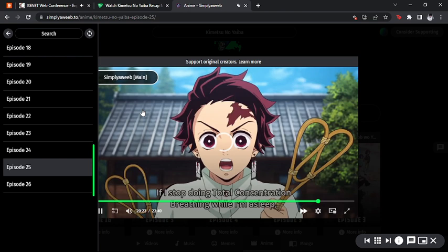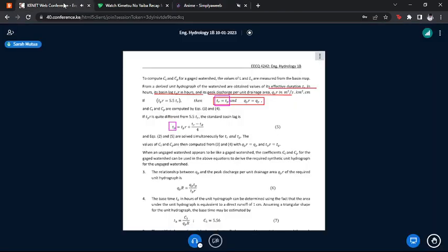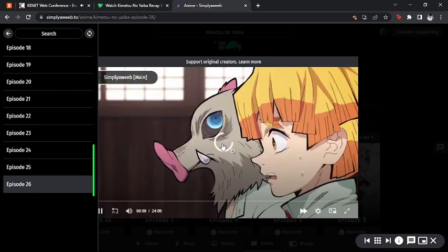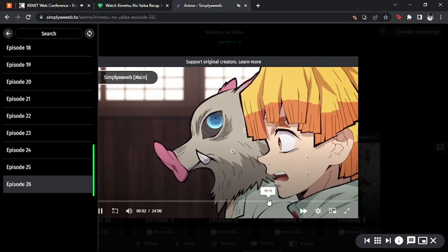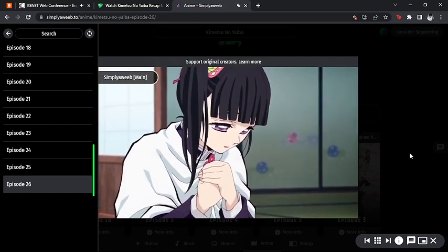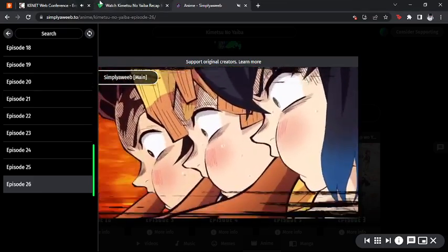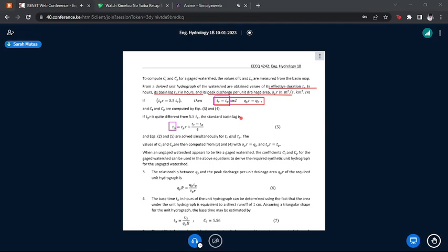And then you can solve equation 2 that we stated earlier and equation 5 simultaneously to solve various characteristics of the hydrograph. Notice in this kind of Snyder's method, we correlate the unit hydrograph characteristics with characteristics of the catchment. What are the characteristics of the catchment here? We have lengths, we have basin time lags, and that is what we are correlating.